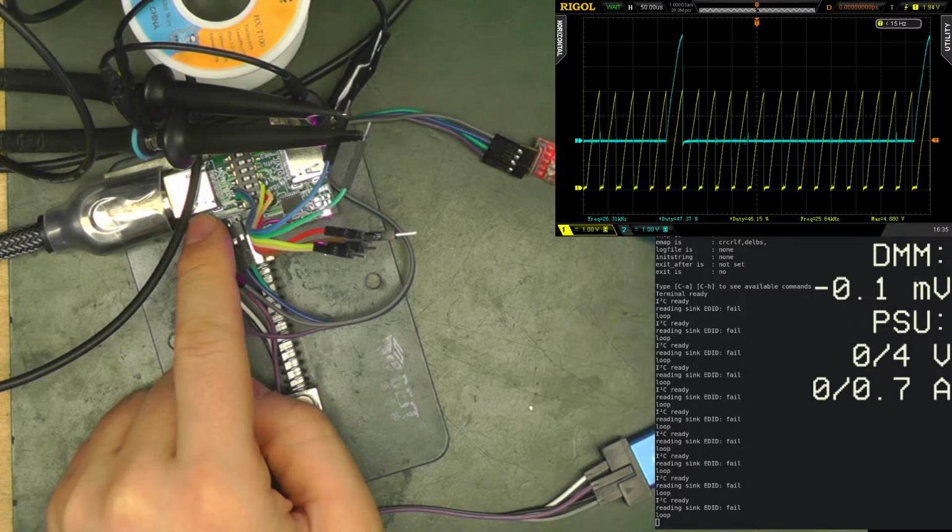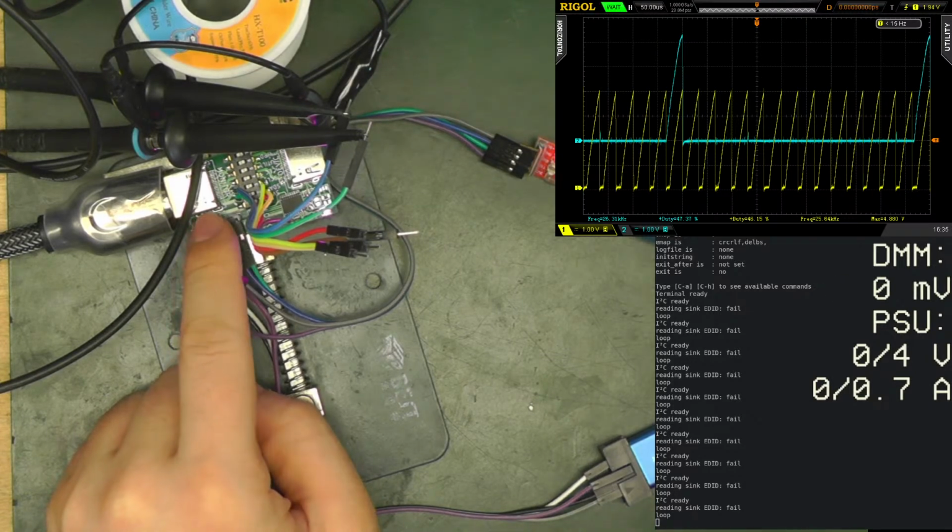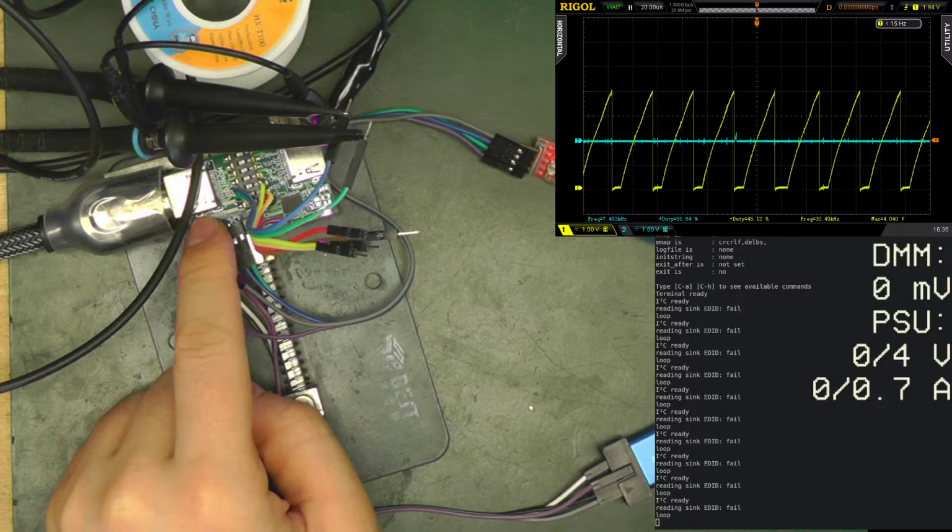I thought there would always be between 1 and 2K. I noted in the schematic, so I read it somewhere in the specification. This is not 1K. The frequency is 30 kilohertz or 25 kilohertz. This is not really fast for I2C, so I need to check in the specification.